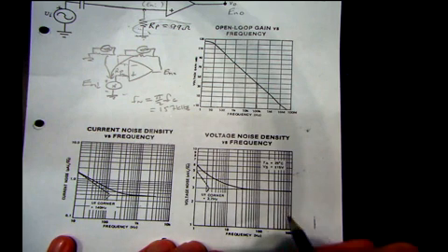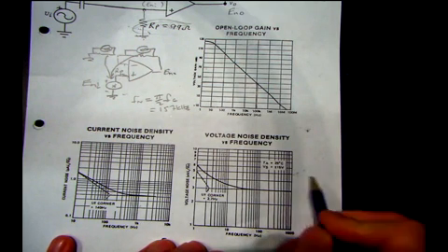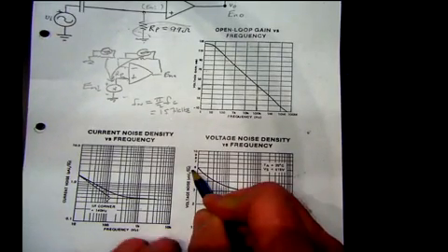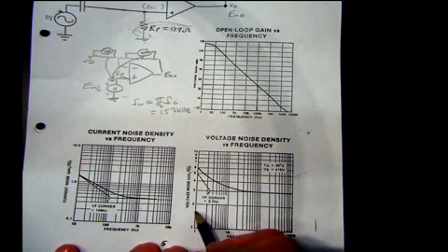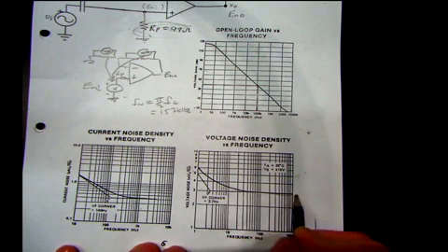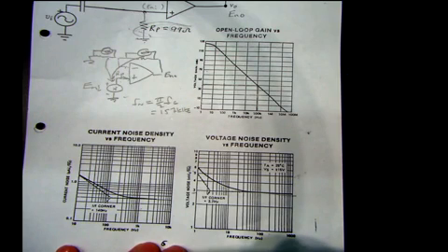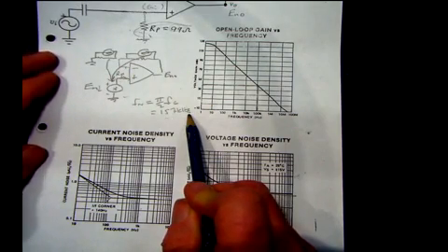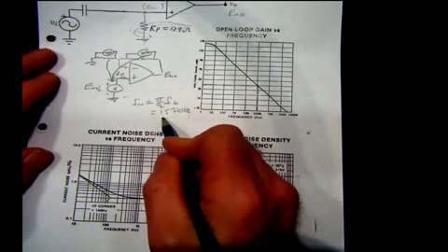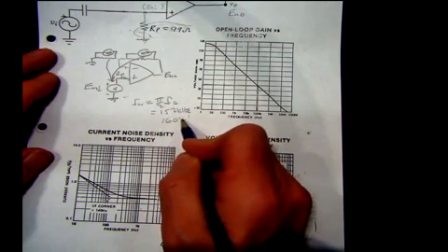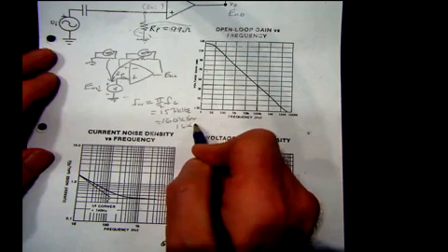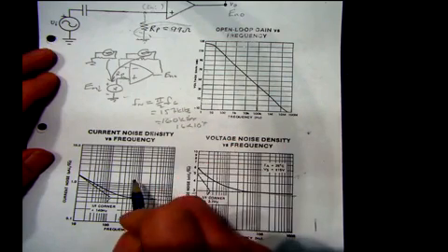Let's imagine we've got units here of nanovolts per square root of hertz, and for the vast proportion there's at least 3 nanovolts, and we've got a bandwidth of 157 kilohertz. How about I call that 160 kilohertz, just to be very rough? In other words, 16 times 10 to the 4th.